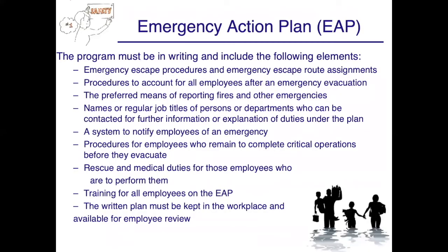So next we will discuss the Emergency Action Plan, or EAP. The EAP must be in writing and include the following elements: emergency escape procedures and emergency escape route assignments, procedures to account for all employees after an emergency evacuation, preferred means of reporting fires and other emergencies, names or regular job titles of persons or departments who can be contacted for further information or explanation of duties under the plan,